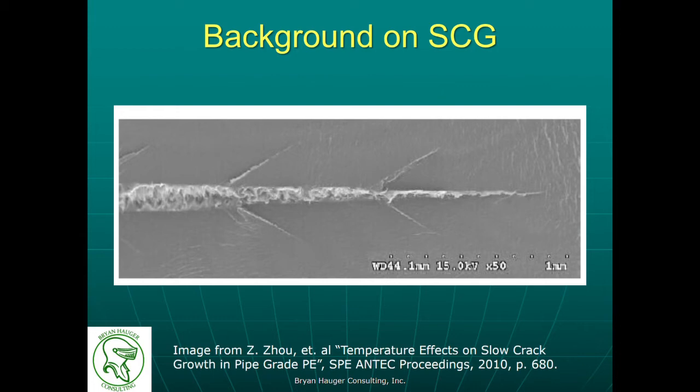The net effect is commonly referred to as crack tip blunting and can temporarily stop the progression of the crack through the material. Eventually, the fibrils thin and rupture, with the crack advancing further through the material. Since the mid-1990s, researchers have been examining the relationship between these bridging fibrils and the drawing portion of the stress-strain curve for polyethylene, amongst a number of other relationships. Eventually, this has all been formalized as ISO 18488.